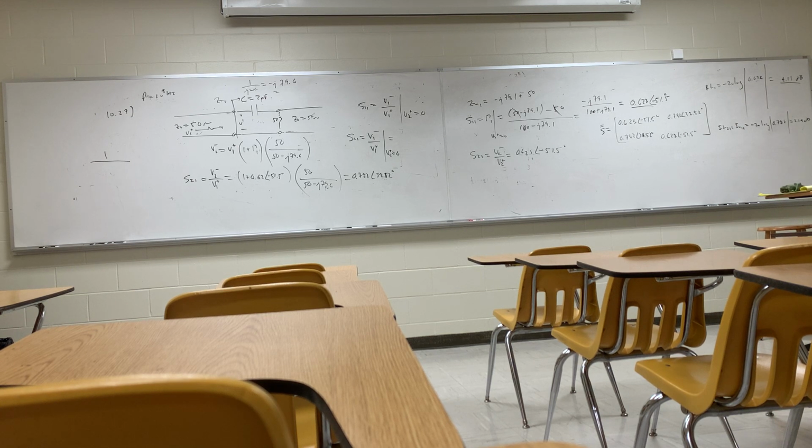Does that make sense to everybody? Now what about the voltage gain? The forward voltage gain is S21. It's V2 minus over V1 plus. If V1 plus comes in and there's no reflection, that is V2 minus, isn't it? So that means the S21 and S12 of that one would be 1. So you would have 0, 0, 1, 1. Y'all follow? This just allows you to get a better feel for these parameters.